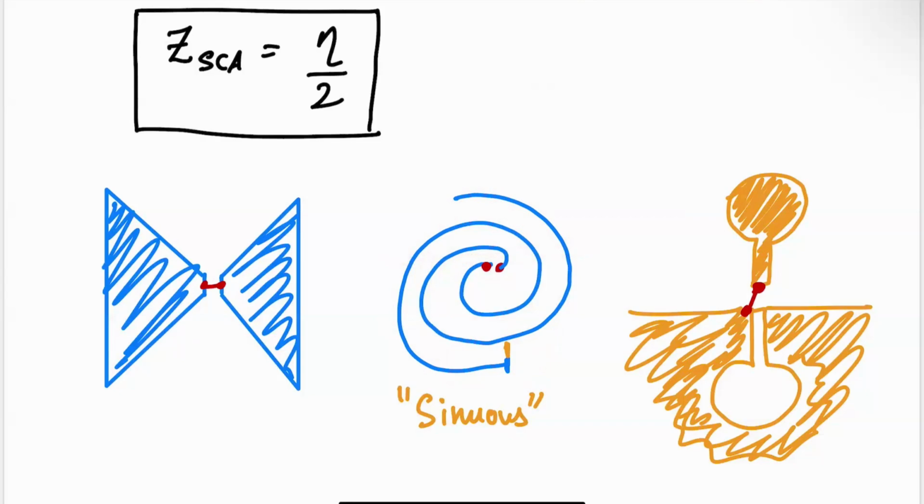And again, this kind of dipole is also somewhat decent in terms of radiation pattern. But then again, if you have a sinuous antenna or a spiral antenna, you don't get linear polarization that easily. It's usually circularly polarized, whereas these dipoles can give you linear polarization and so on. So there are many other considerations than just the bandwidth. And of course, Babinet just tells you about the impedance bandwidth. It doesn't give you any guarantees of good radiation performance or good radiation characteristics over the entire band. And so all of that needs to also be taken into account when you're doing antenna design. So I just wanted to mention that.